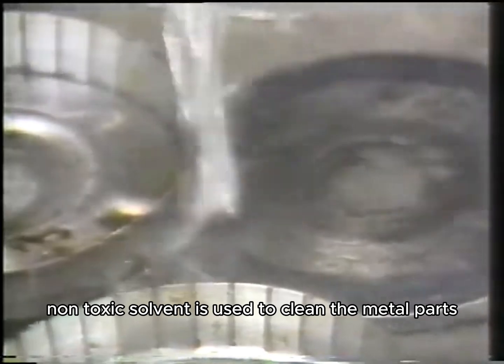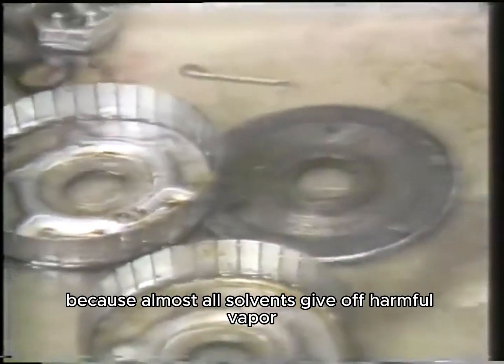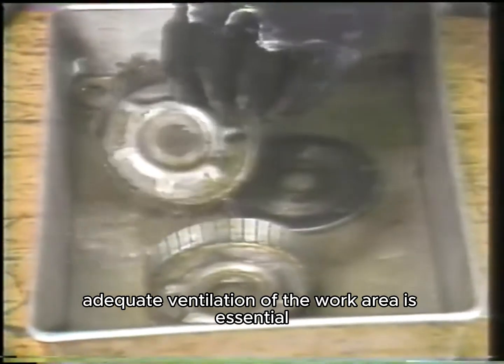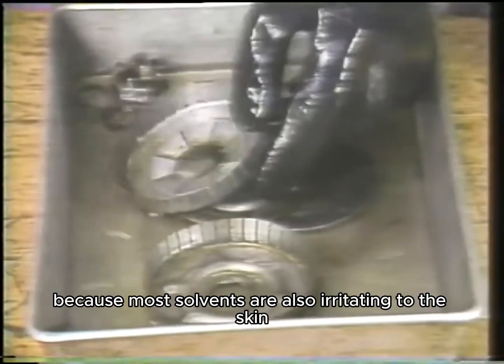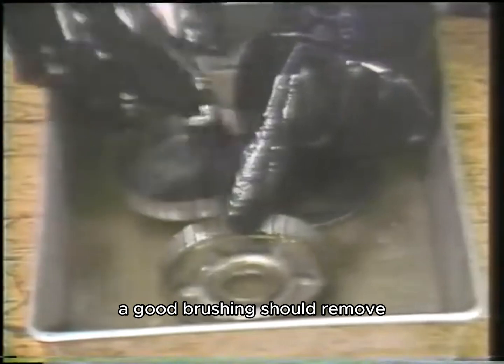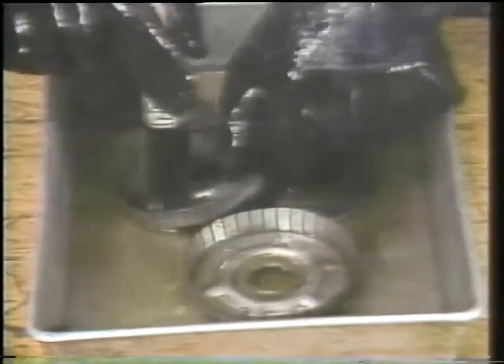A non-flammable, non-toxic solvent is used to clean the metal parts. Because almost all solvents give off harmful vapor, adequate ventilation of the work area is essential during this part of the job. Rubber gloves are also helpful because most solvents are also irritating to the skin. A good brushing should remove all of the built-up grease and dirt on the parts.